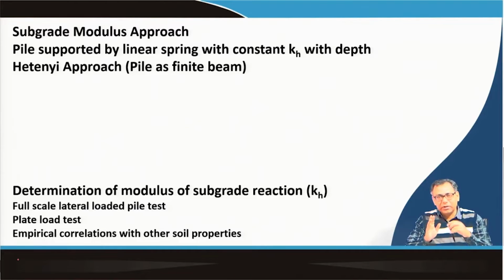In that case the springs were vertical springs and the beams were resting on them, but that concept will be used here for laterally loaded piles, where the springs will be horizontal springs.